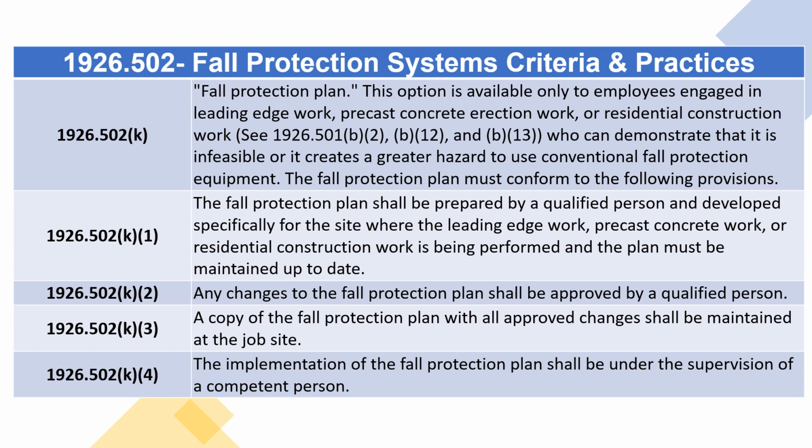1926.502 K1. The fall protection plan shall be prepared by a qualified person and developed specifically for the site where the leading edge work, precast concrete work, or residential construction work is being performed, and the plan must be maintained up to date. K2. Any changes to the fall protection plan shall be approved by a qualified person. K3. A copy of the fall protection plan with all approved changes shall be maintained at the job site. K4. The implementation of the fall protection plan shall be under the supervision of a competent person.